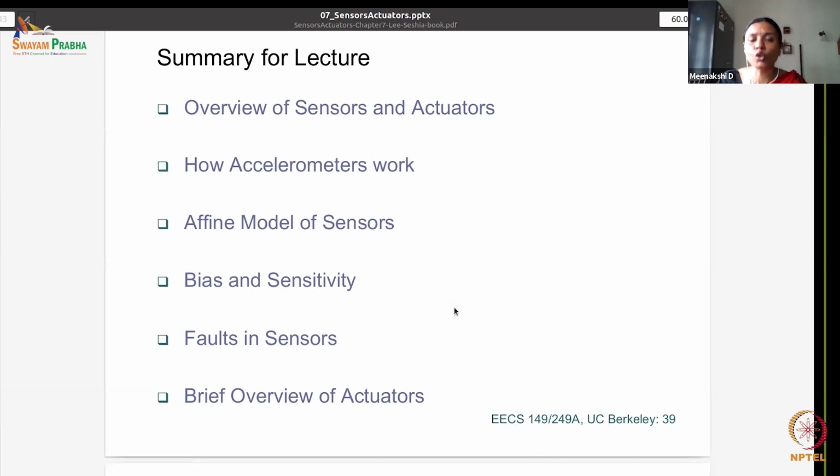And then how do I read input-output mechanisms? As we told you, sensors read from the physical world. We would want to use them in our cyber world, or our computing world. So how do we do it? The physical world is continuous, the computing world is discrete. So we use polling as one mechanism. We also can use interrupts as the other mechanism.